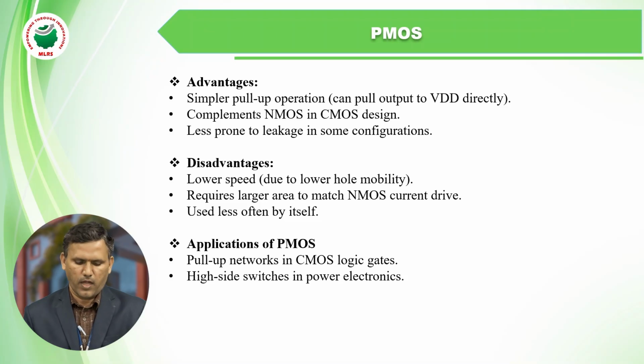Disadvantages are lower speed due to the lower hole mobility. It requires a larger area to match the NMOS current drive. Used less often by itself. Applications of PMOS are pull-up networks in CMOS logic gates and high-side switches in power electronics.